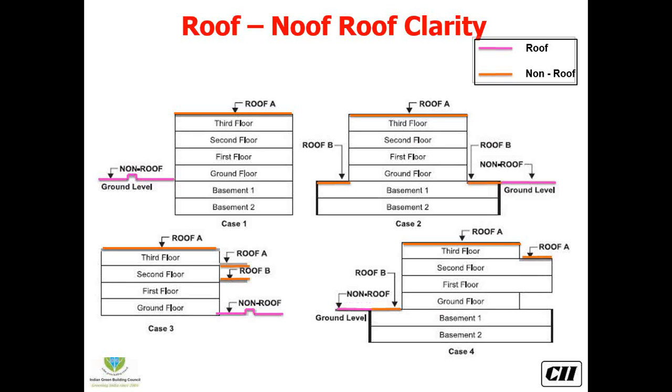In the case of case 2, roof B, which is acting as a podium, since normally we circulate in those areas, we prefer to go for lower SRI materials. And such roofs can be addressed through grid pavers, grass pavers, or lower SRI values between 29 and 69. If you see case number 3, even though there are 2 projections, roof A and roof B on the right hand side, roof B is also recommended to have lower SRI values, because such values will affect the occupants who are in the building, whereas the top surface of roof A can always go for higher SRIs.